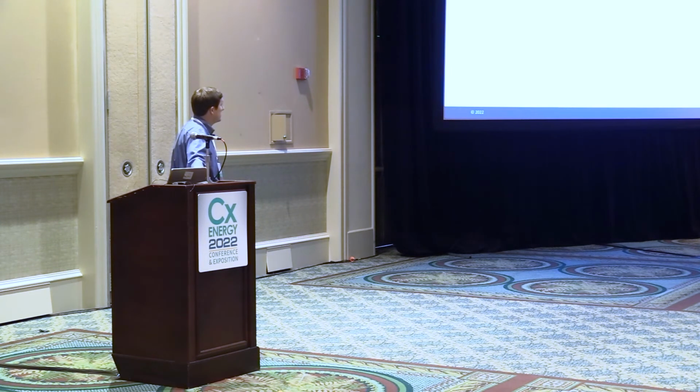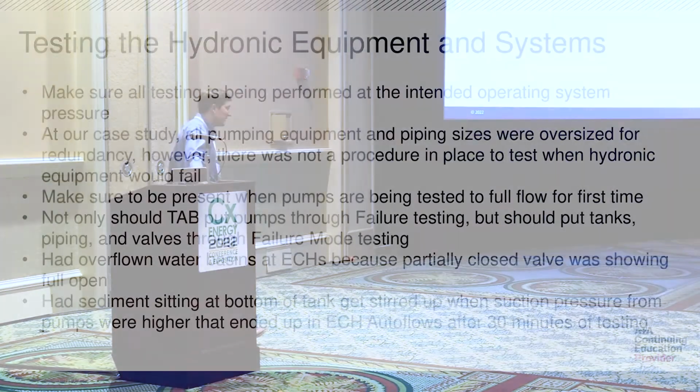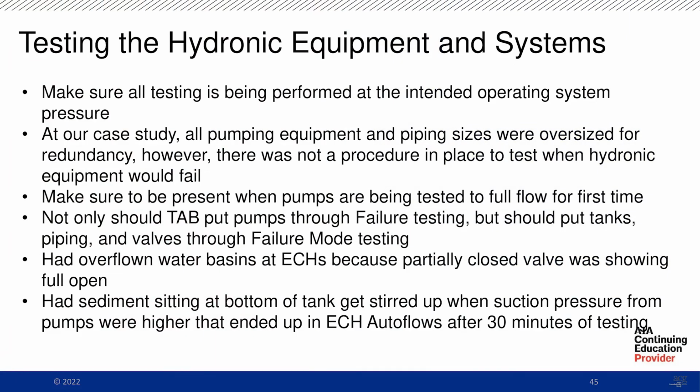Also make sure to be present when pumps are being tested at full flow for the first time. Because these are such large pieces of equipment, I remember walking into the room and it sounded like someone was making concrete in there. Every single pump was at 60 hertz and every single one was cavitating. So please be present when your controls guy decides to run a pump up.